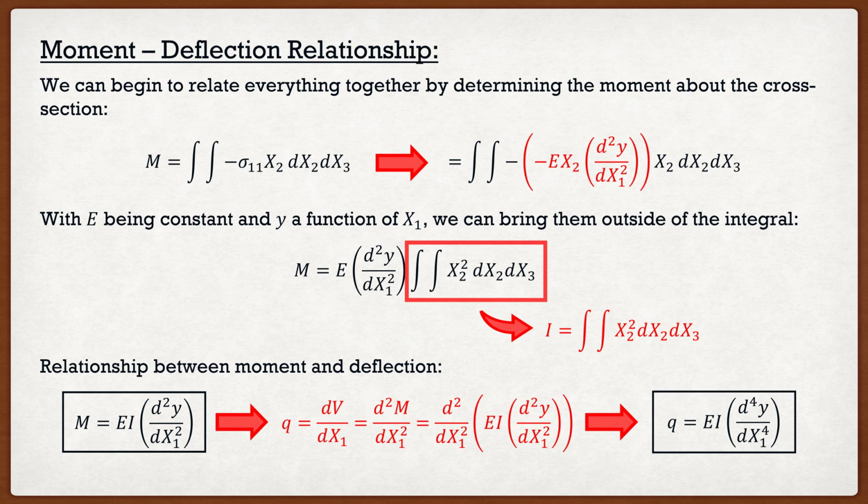Well, if we're designing a beam, if you are designers in an office and they give you a beam, the first thing that they will always give you is what the loads on the beam are, aka what Q is. So if we look at this equation, we know what Q is. We almost always know what EI is, so that's not going to be a problem. Our only unknown now is going to be that deflection function. Therefore, we can solve for that deflection function.